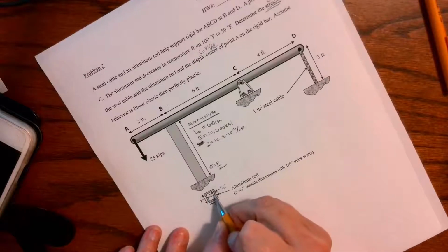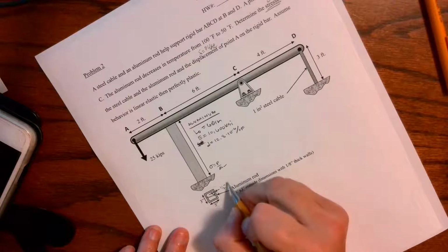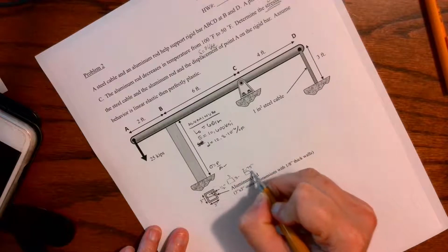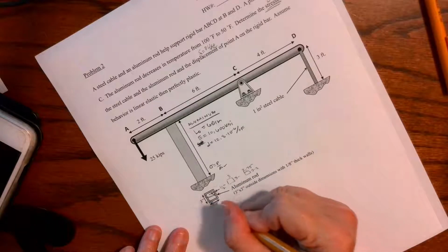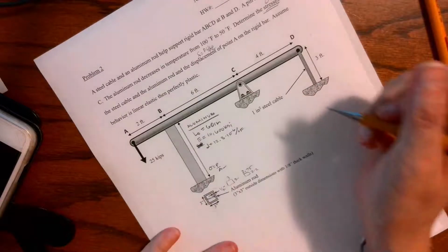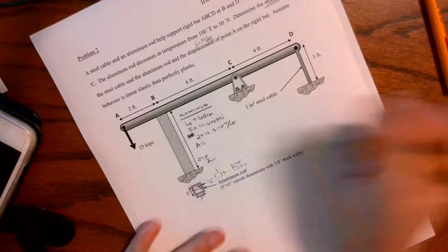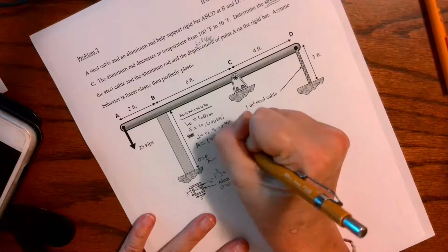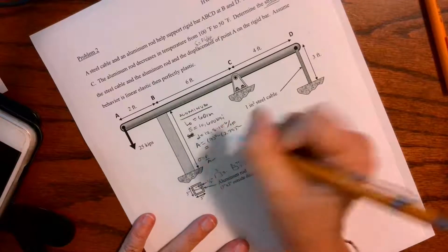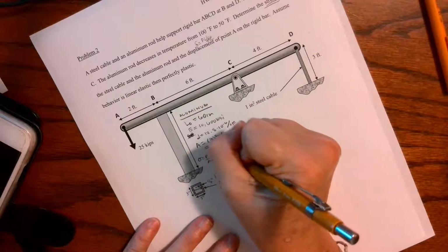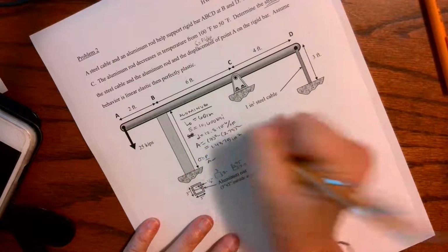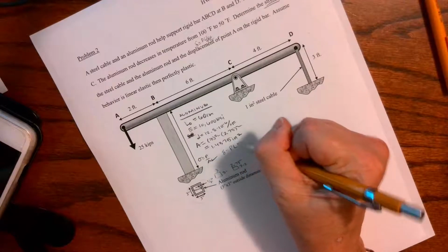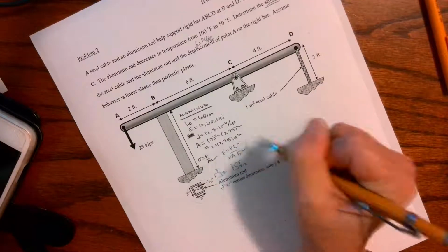So I know the inside dimensions are 2.75. So I'm going to take an outside of 3 by 3 minus an inside of 2.75 so that I can calculate the gray area that's remaining. Okay, so if I look at my area, it is going to be 3 squared minus 2.75 squared, and I get an area of 1.4375 inches squared. So I can do my stress. I could do delta equals PL over AE. I have everything right here.